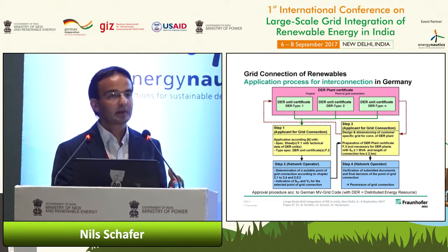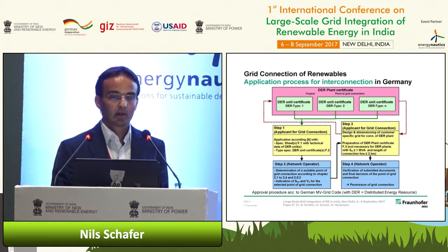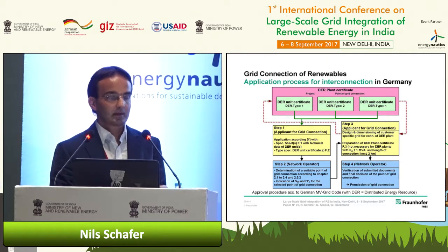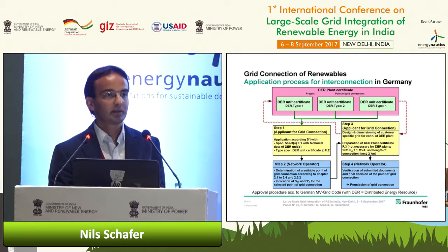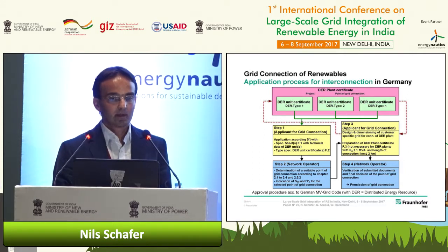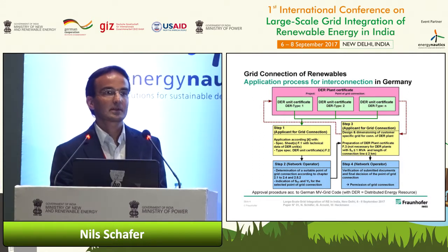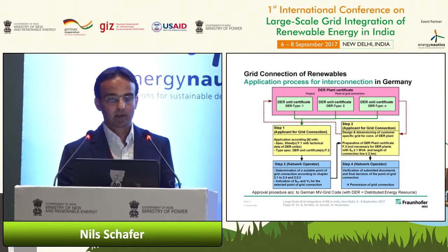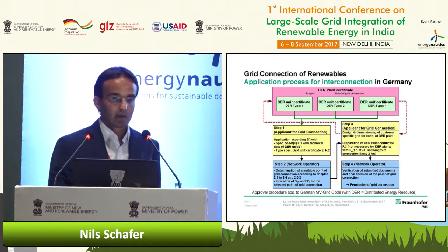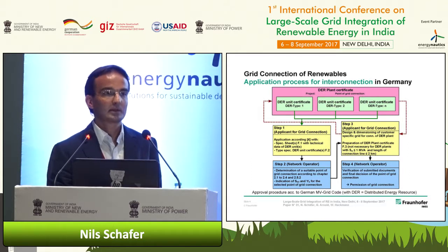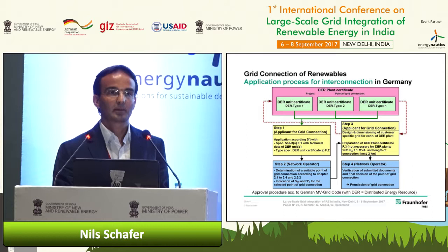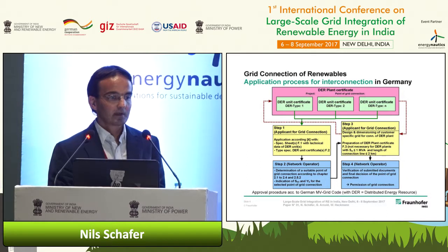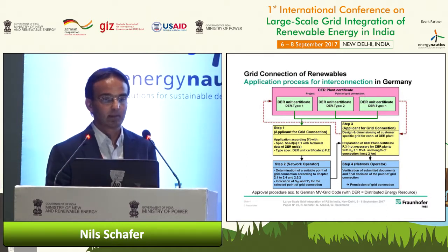And for all different types of inverter or wind turbine, a separate unit certificate is necessary. If you have different types of inverters or wind turbines, you may have more than just one unit certificate. Taking these unit certificates, you also consider lines and transformers of your park, and altogether the plant is set up. So a plant certificate is set up by this.